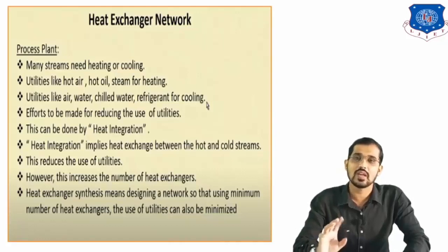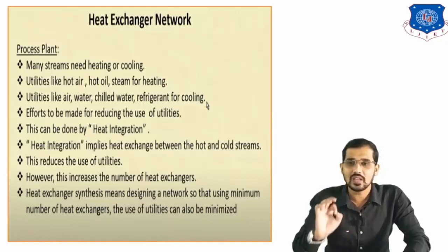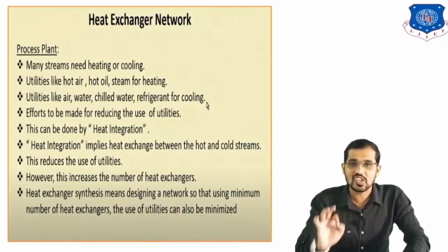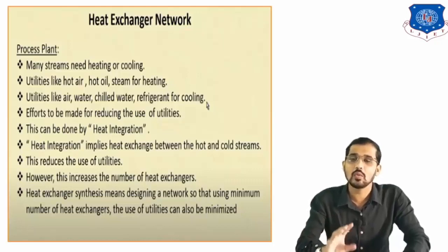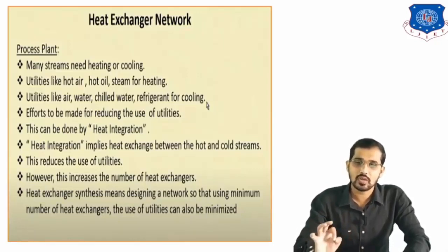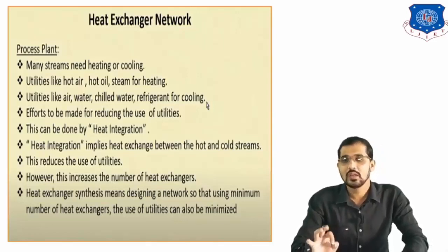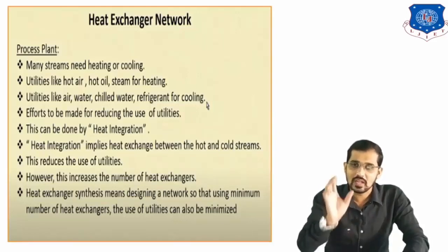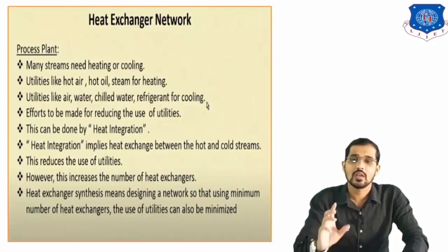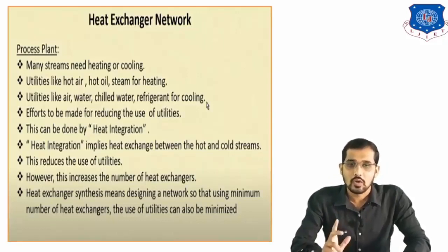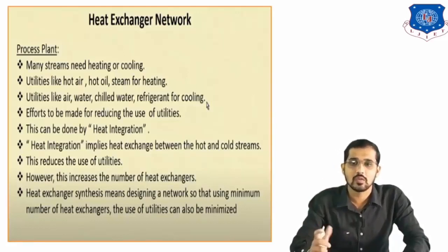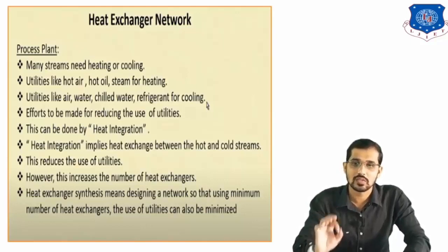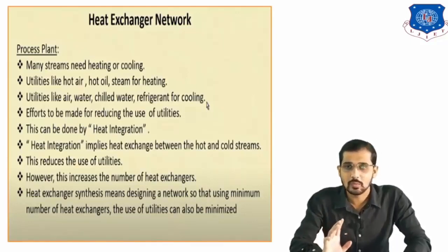Heat integration means we are exchanging heat between the cold and hot utilities. You can see on the screen, heat integration implies heat exchange between the hot and cold streams. We are exchanging heat between the cold and hot streams. This is a very important concept for your GATE examination as well, where a question may be asked like this: identify the concept of heat integration where we are exchanging heat between the cold and hot utilities. Or I can say, how to minimize the hot utilities and cold utilities. By using the heat integration concept, you can accomplish this.